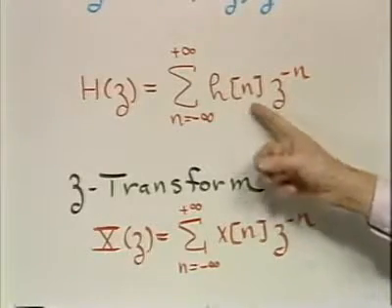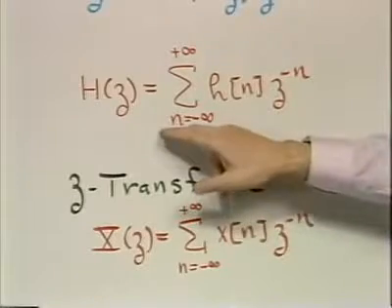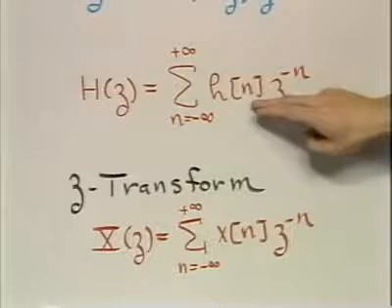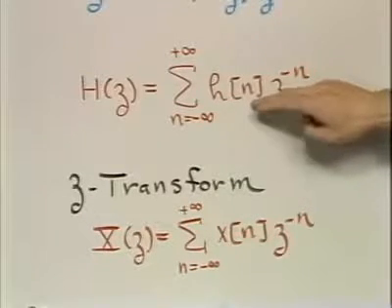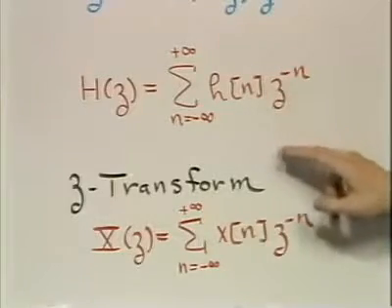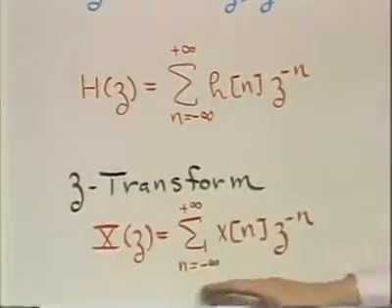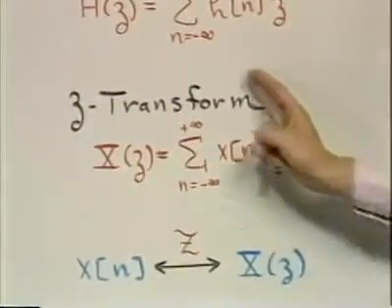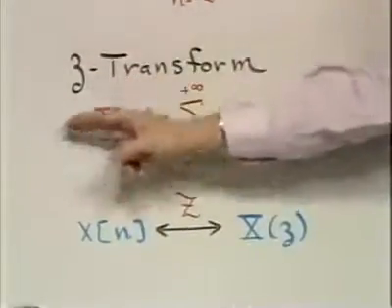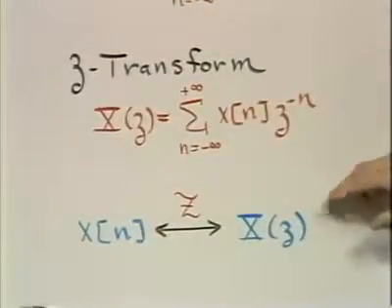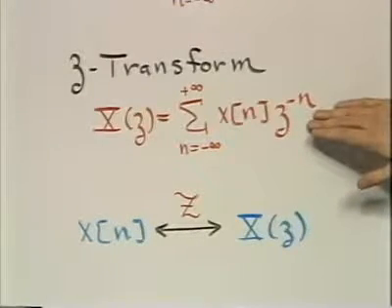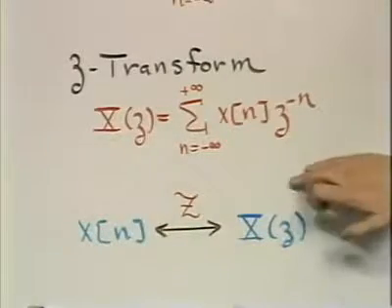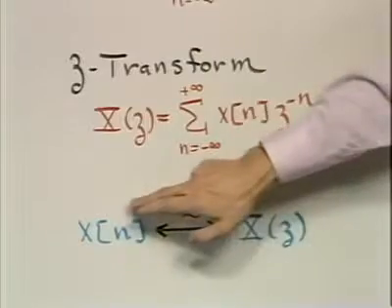And if we consider applying this mapping, as we did in continuous time in a similar argument, to a sequence, whether or not it corresponds to the impulse response of a linear time invariant system, that leads then to the z transform of a general sequence x of n, the z transform being defined by this relationship. And again, notationally, we'll often represent a time function and a z transform through a shorthand notation just indicating that x of z is the z transform of x of n.